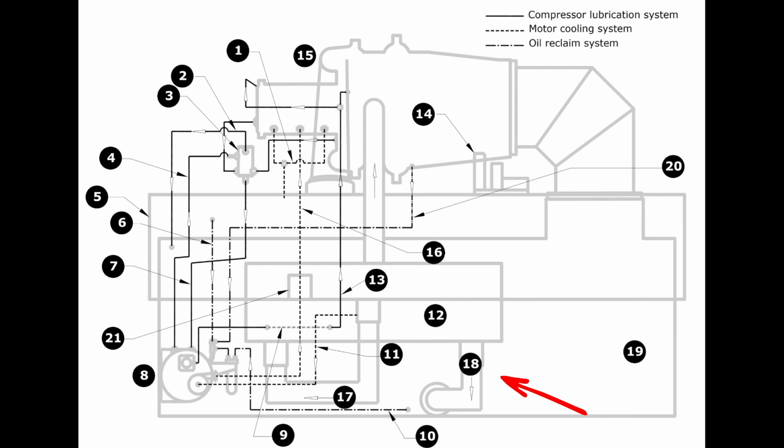There's a sight glass in that eductor return line, and we've got to tune that valve based off of that sight glass once the machine is in full operation and we've got the liquid level calibrated into the evaporator and all that's set up.